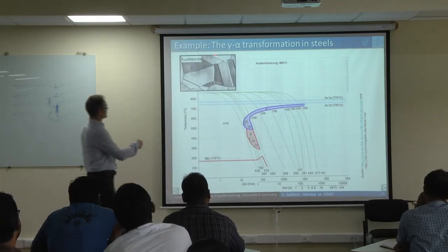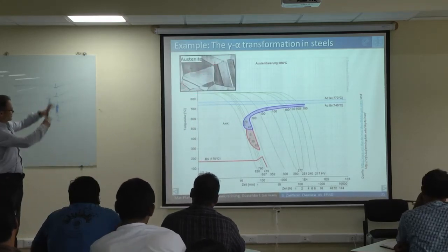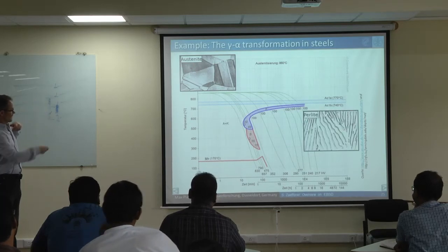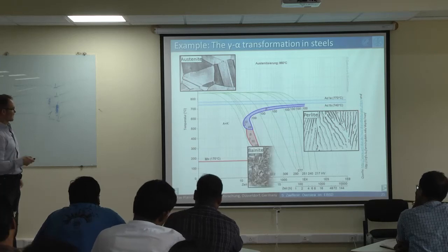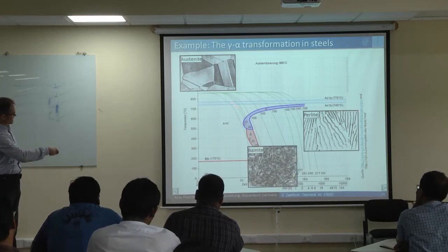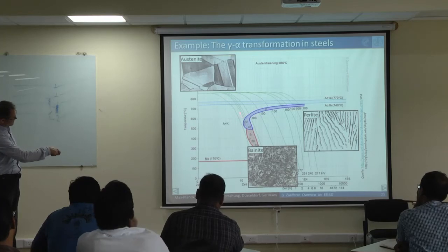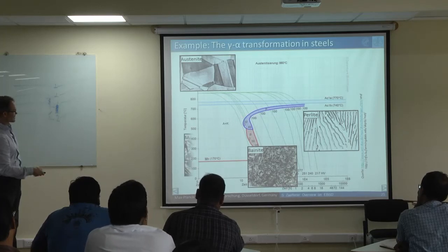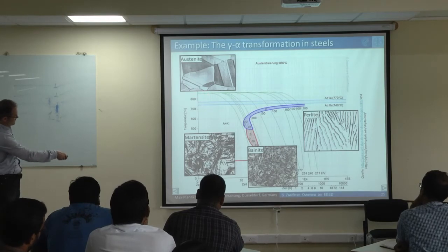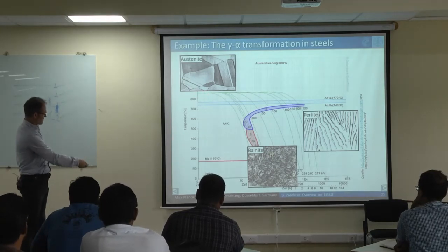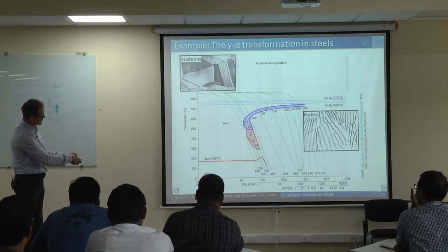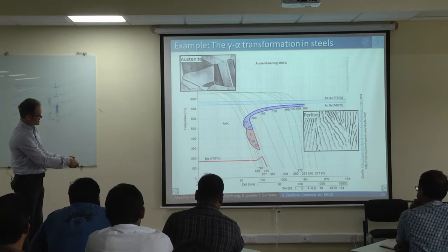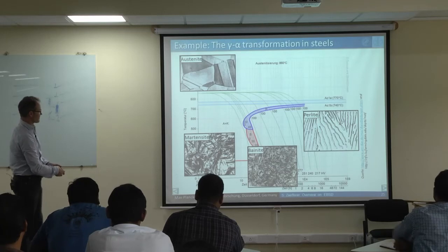And actually, so we start with purely austenite, big grains of austenite, and if we cool it down along here, we get a purely pearlitic structure. If we cool down along the bainitic, through this pearlitic bainitic area, we get a bainite structure. If we cool down very rapidly, avoiding touching these noses here, then we transform the microstructure into martensite, or bainite martensite.